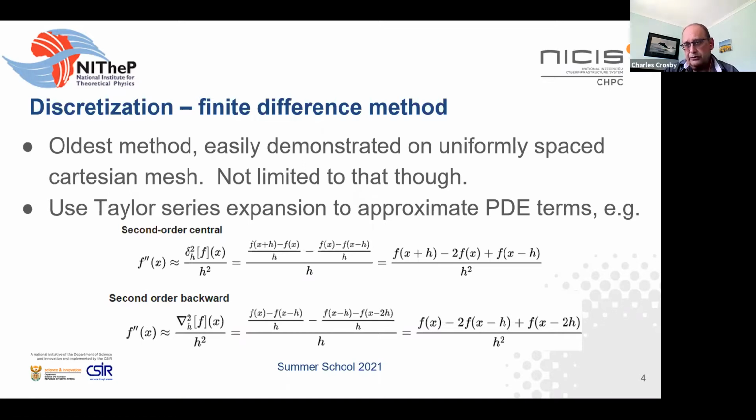Remember, we had the four terms, a transient term, a convection term, a diffusion term, and a source term in the transport equation. And the convection term is something that's evaluated at the boundaries of your control volume. So you're looking at the flux of momentum or whatever it properly is, temperature, chemical species, etc., across that face of the control volume, or the finite volume.